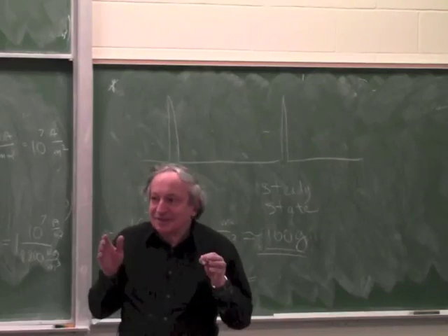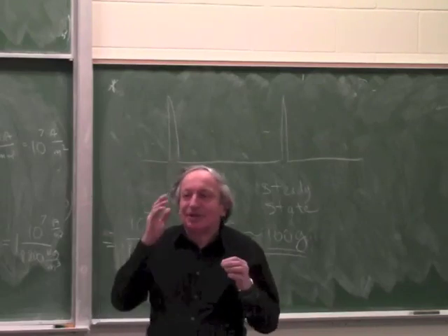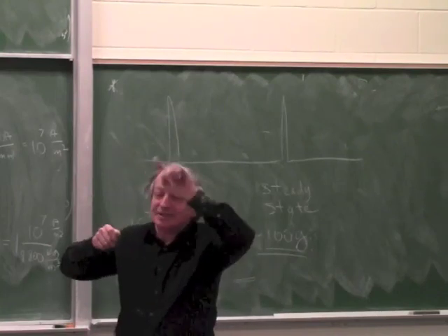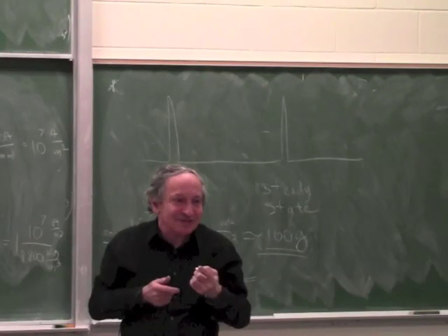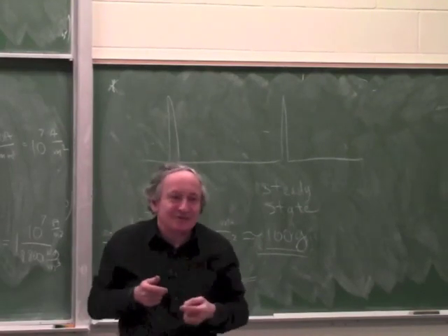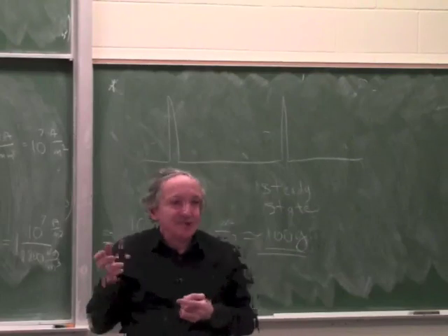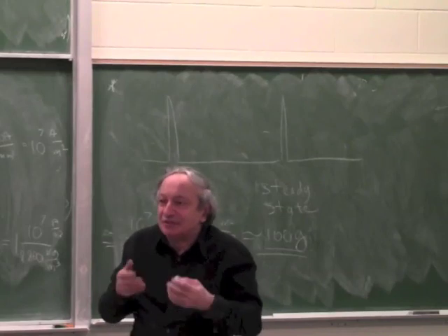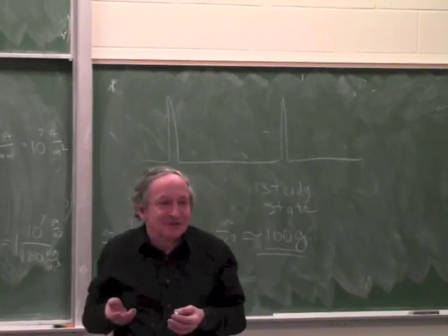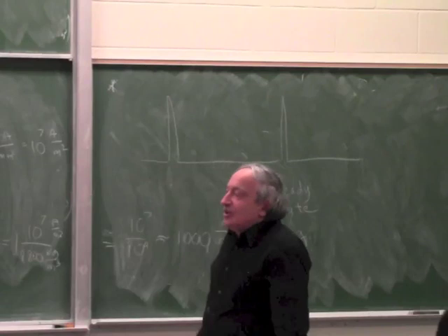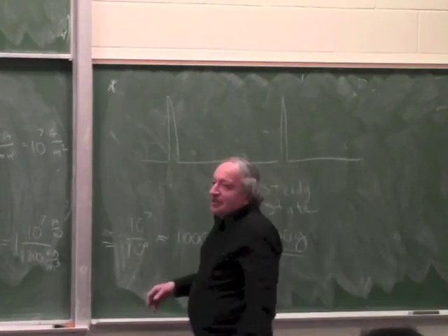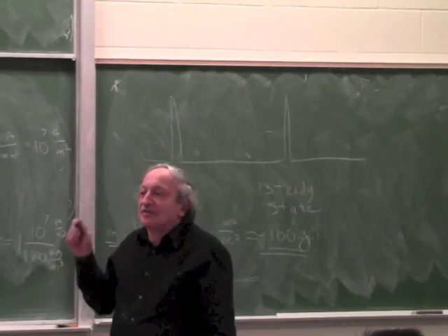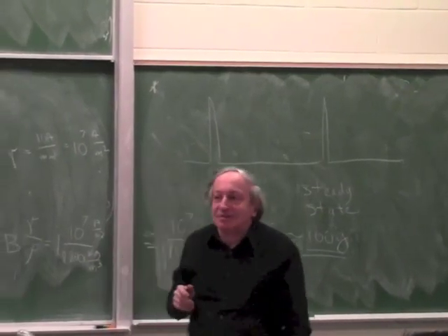Is that clear? Because otherwise you'd be tempted to think, maybe I can make a clever coil in which one term goes this way and another term goes backwards to cancel the impedance. But it's a waste of time, because if you cancel the impedance, you cancel the stored energy, which comes from impedance. And if you cancel stored energy, you cancel the derivative of energy with respect to distance. It will give you no force. Okay? Good. So I can get rid of the impedance by driving it from a current source, or by making a coil which has very few turns driven at very high currents. But there must be some other limit.